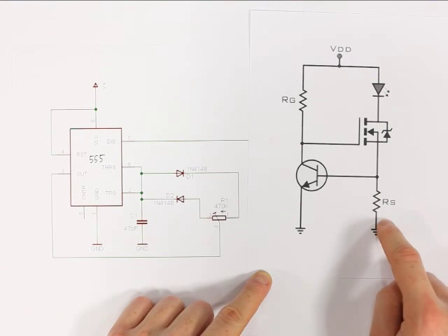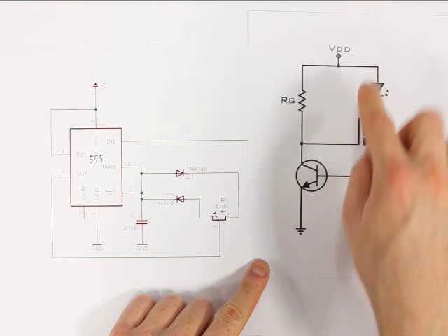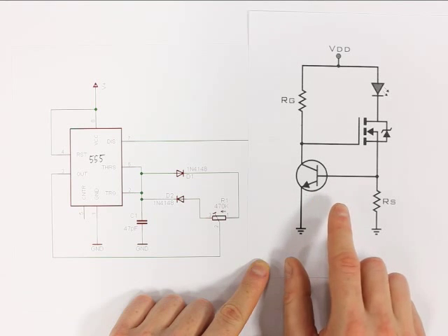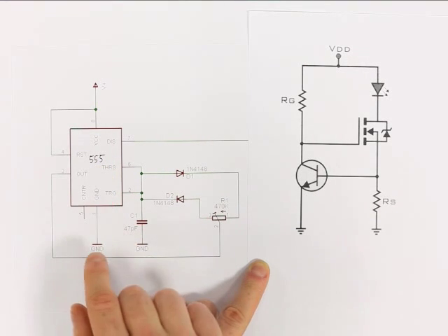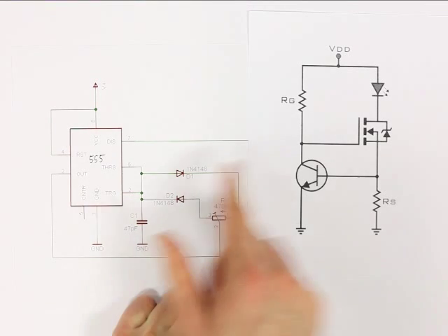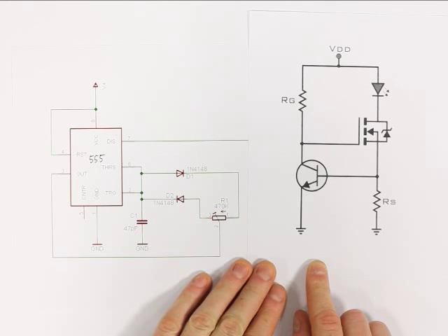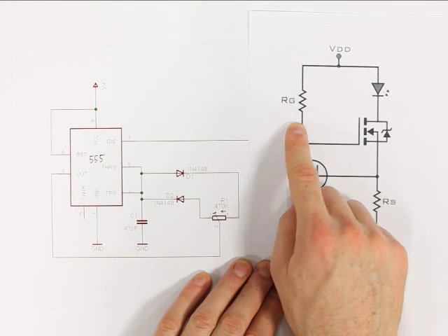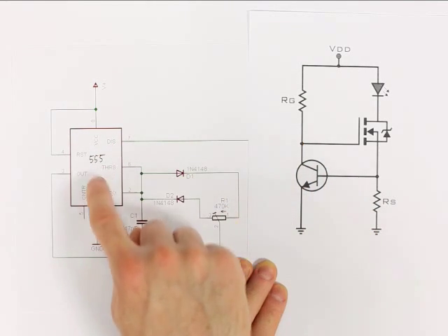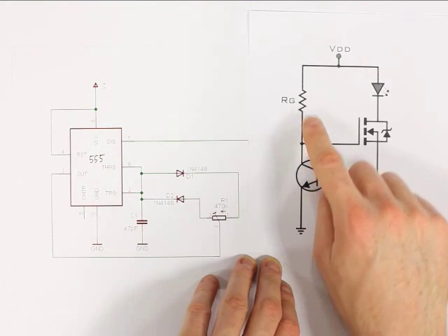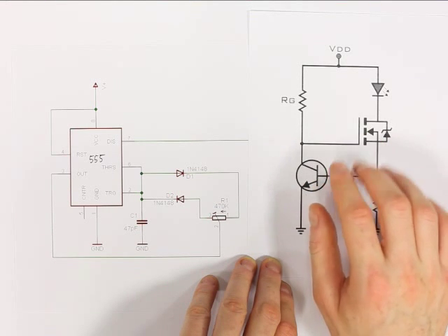With no current through here, the BJT also shuts off. So we have only a tiny amount of power being consumed then. We'll have whatever is required to operate the 555 timer, which is fairly small compared with the LED. And then we will have the tiny amount consumed by RG, because current will flow through RG through the 555 timer to ground. And that was calculated at only 1 milliamp, so that's quite small.